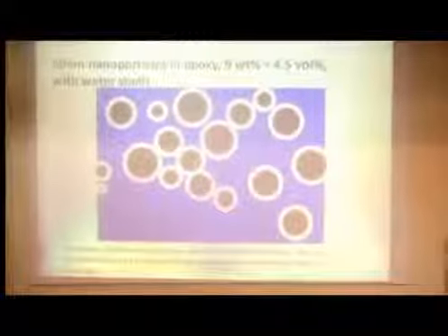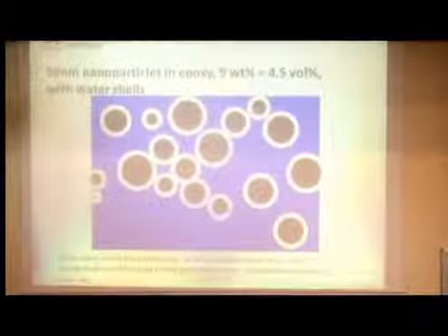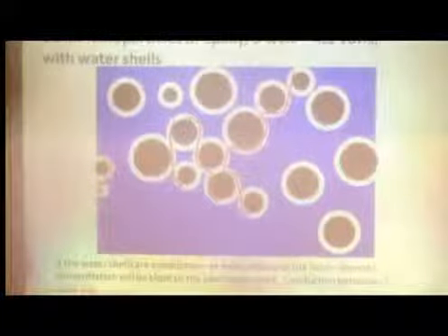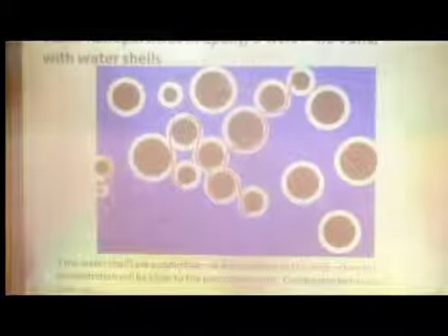Well, let's first of all start off by having a quick look at conduction and polarisation. So, going back to these 50 nanometer nanoparticles of epoxy, 9% by weight, 4.5% by volume, with water shells, we'd expect these to increase in conductivity because we're now above the percolation limit, or at least very close to it, and we therefore expect to see quite long-range movement of charge through the water surrounding the particles.